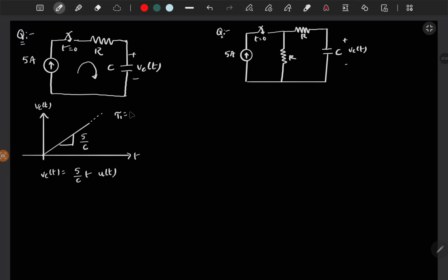And here also time constant is infinite, but if you find the time constant here, then open circuit this one, then you will have a finite resistor across the capacitor terminals, which is C times those two resistors in series. You will get 2 RC as time constant. So since it is first order and time constant is positive, you will get exponential behavior.